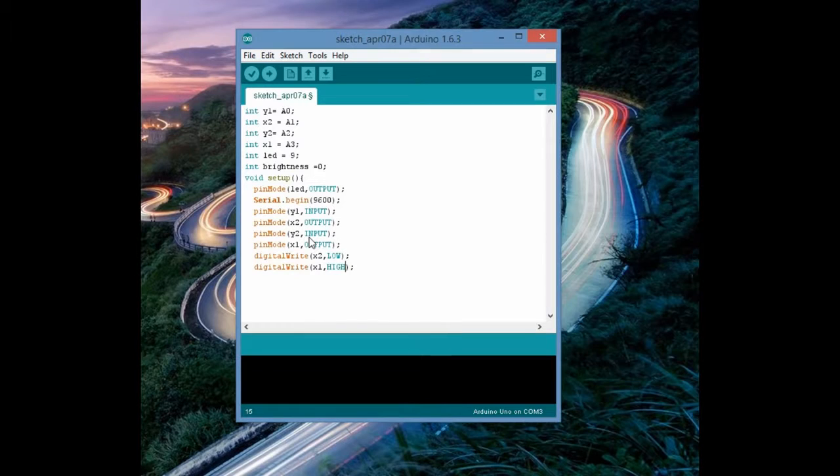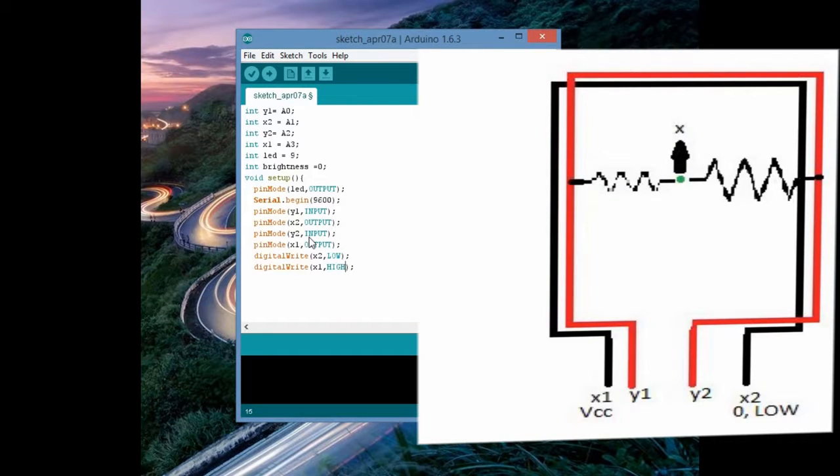So when we press on the touchpad, these two values will give the potential difference at the point from where we are touching. When the X plate is having the power, and we touch across the Y plate, there is a difference in resistance, and applying the voltage divider rule, we get the potential at Y1 and across Y2, where Y1 and Y2 are complementary to each other.